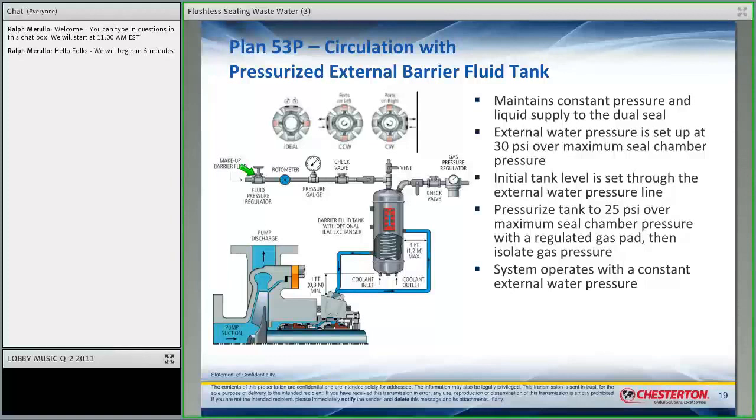You like that seal to be pressurized at least 15 psi above the sealed pressure in the pump. That way, this water will lubricate the inner seal and the outer seal, right? So what you have here is a seal that's impervious to ragging out. If you have fiber collecting all up inside this seal chamber, doesn't matter, right? The seal will work.